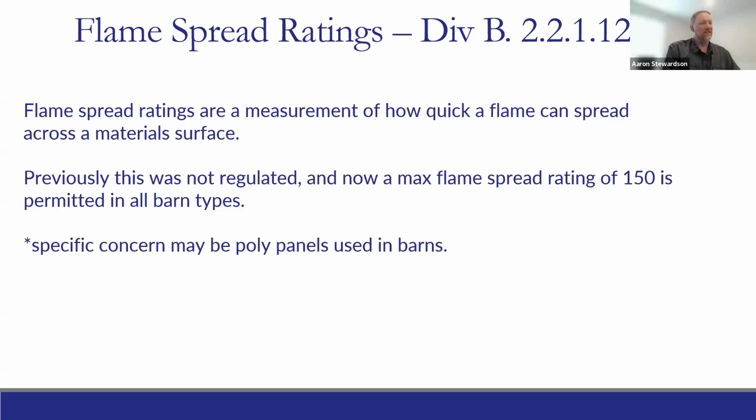So it's a change, but it's not going to be too hard to overcome. It just means that you're into a product that has to have a rating that's proven, right? The majority of the polys that are used generally do meet this flame spread rating. So there shouldn't be too much of a concern there for anybody, but it's just something that you may be asked to provide. And something you need to be prepared for is that when a building official, we're just looking to prove that it meets, right? So your designer may have to just have the information that comes from the supplier proving that this material meets the flame spread limits.